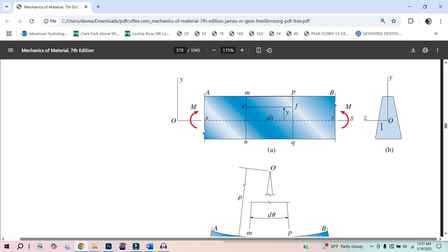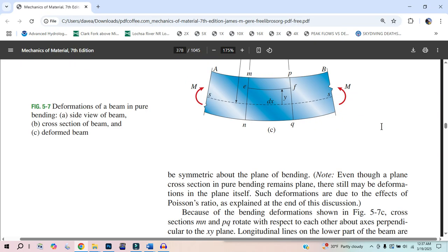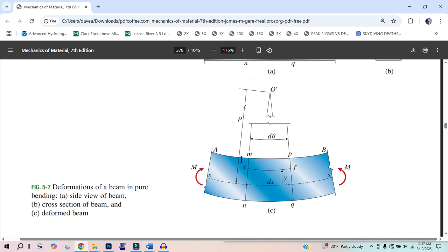It comes down to this curve, the moment causes the shape, and we have a strain up here. So the first part is to figure out what the equation is. You're going to have no strain here. So when y is equal to 0, you're going to have no strain. The other thing is when this causes a radius, you're going to have a little wedge, a slice of a pizza, like a pizza slice of a bigger circle.